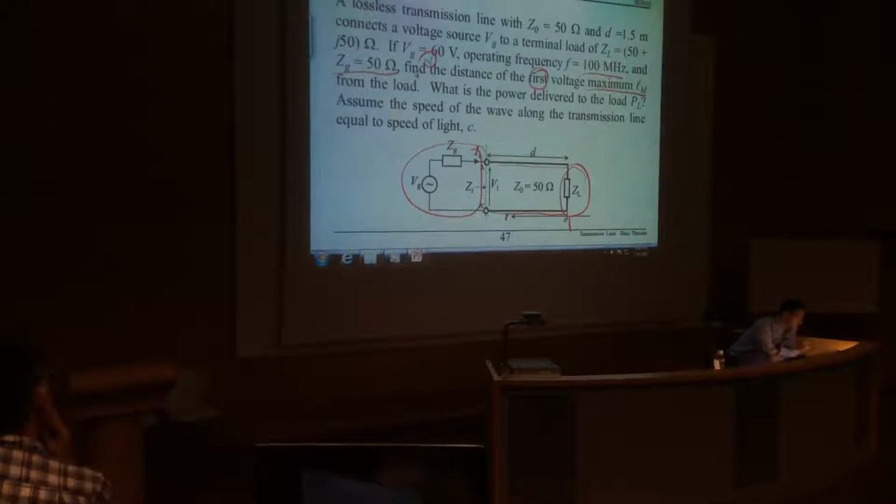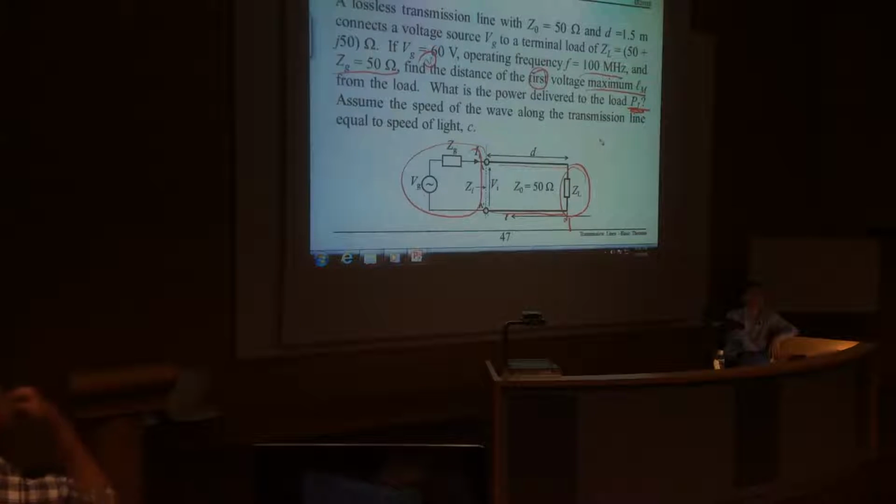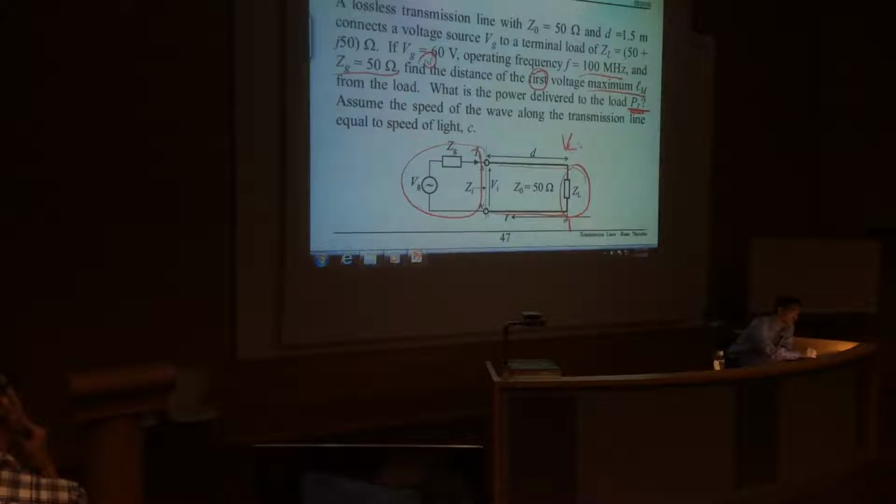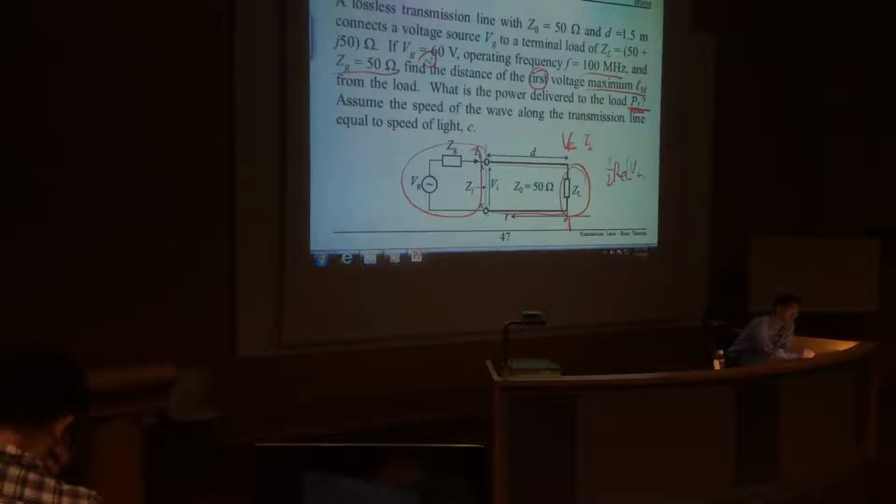Question 2 is, what is the power delivered to the load? You have two approaches to calculate. One is to calculate the voltage and the current at the load, then by using the equation, use the real part of VL, IL to calculate.